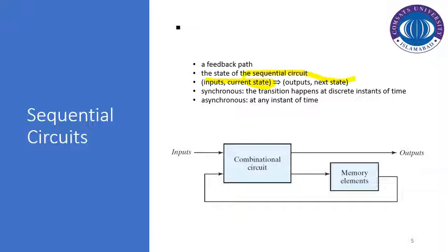So it's not possible that at every time instant the transition to the output is possible. We've got some specific time frame or time interval or time instant that is responsible to produce the output. So the output is basically sensitive to some specific timed information that is being provided to the circuit. As far as the asynchronous sequential circuits are concerned, the transition to the output can happen at any instant of time.